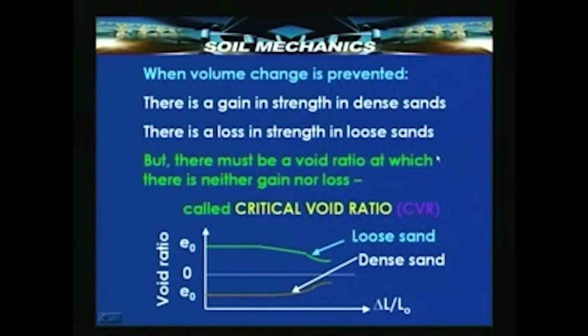Whereas in the case of loose sands, if we do not permit volume change, we are preventing the sand from becoming denser and gaining more strength. Therefore it actually loses strength.